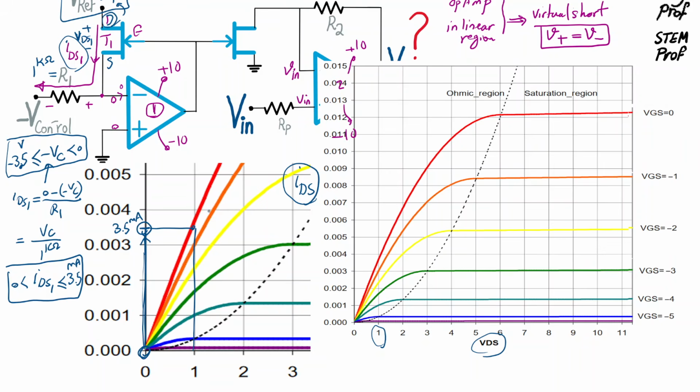So it means in the ohmic region of operation of the IV curve of the JFET, we are in this range, which we zoom in here, and we see that the relationship between the current and voltage of the JFET is a very linear relationship, like either the red one or orange one or the yellow one or the green one or the other different green, and then finally at the lowest the blue one, which we don't get there.